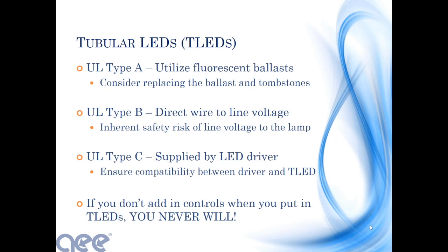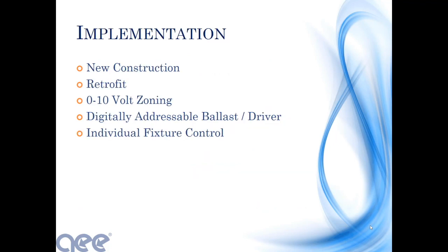The one thing that I will say, we do a lot of performance contracting work, those types of things. If you don't put controls in when you change your fixture, you'll never put controls in, because your ROI just won't work since your connected load is already lower. Your labor cost is double because you have to go back up and down on the ladders. You have to do that twice. So your ROI just doesn't work if you don't do controls at the same time that you do your fixtures, whatever technology you use. Okay?